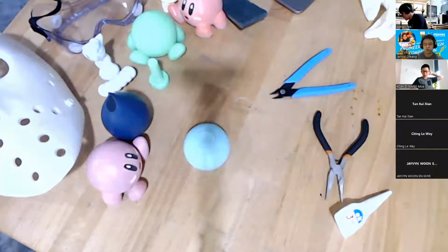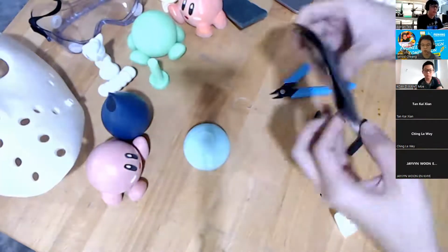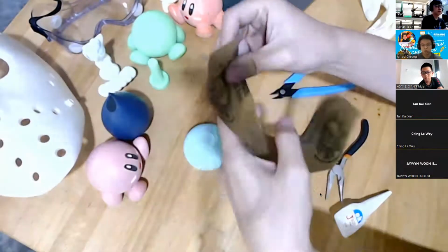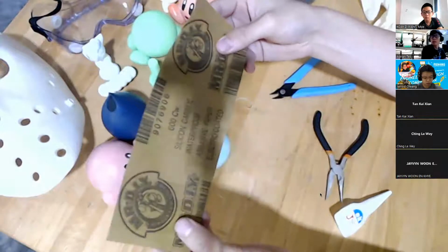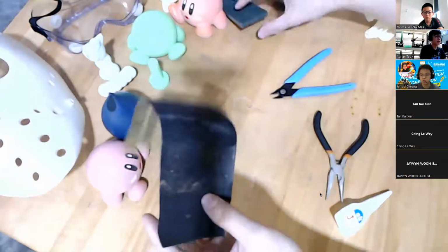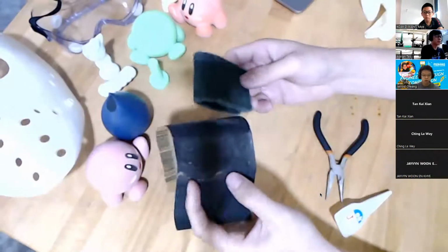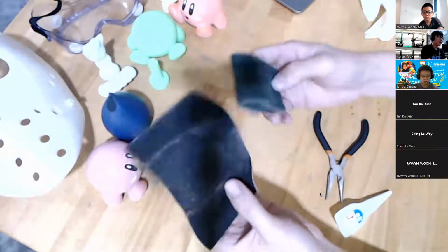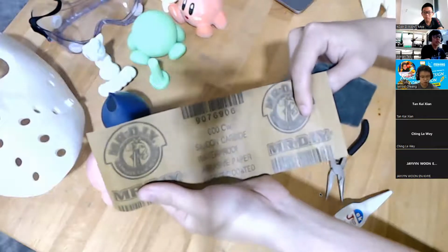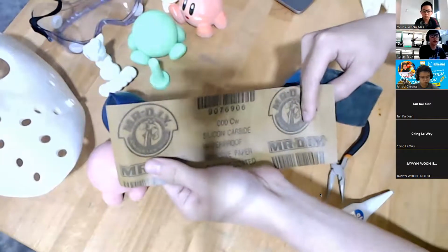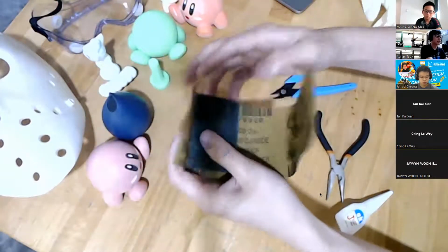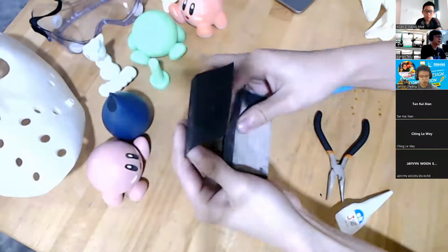All right. Next, you will want to cut your sandpaper into smaller pieces like that. Cut it this way so that it's easier for you to wrap it together with the sponge. That's where the sponge comes in. So how do you wrap it? Right now I have a 600 grit, just to show you an example, but of course you start with a lower grit first, 120, before you go to 600. So I put my sponge here and then I just cover it this way.